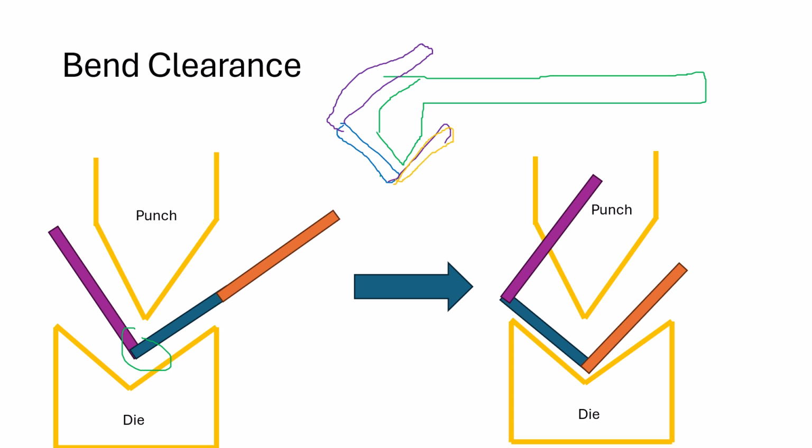You might have trouble now removing it from the machine. I mean, obviously these things can spring around a little bit. But yeah, it just goes to show that if you have this cup right here with a very deep cup, punching and bending it is just not going to be an effective method to get it done on your standard brake press die. So just something to keep in mind. Like I said, use standard tooling wherever we can.